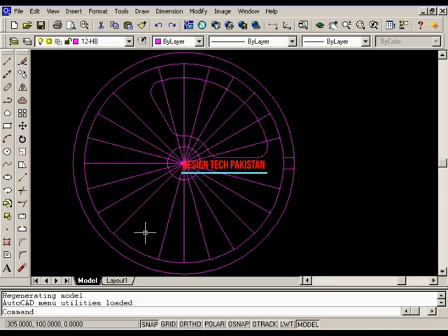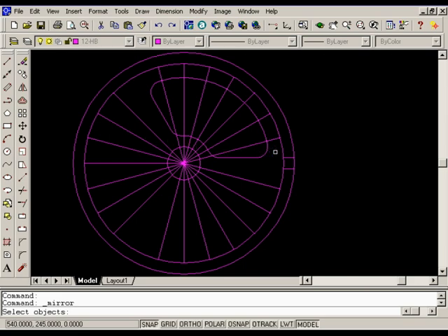Selecting objects using window selection. On the Modify toolbar, choose Mirror. Click above and to the left and click below and to the right of the two short horizontal lines on the right side of the circle. Objects inside the window are selected.